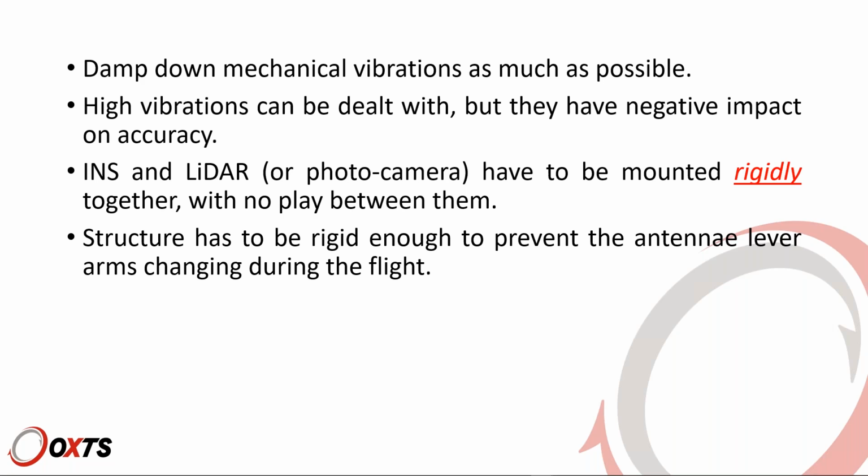They need to move and vibrate, if they have to vibrate, together, because obviously you will use the INS data to reference the LiDAR data, so they need to have exactly the same kind of motion, no play in between them whatsoever.